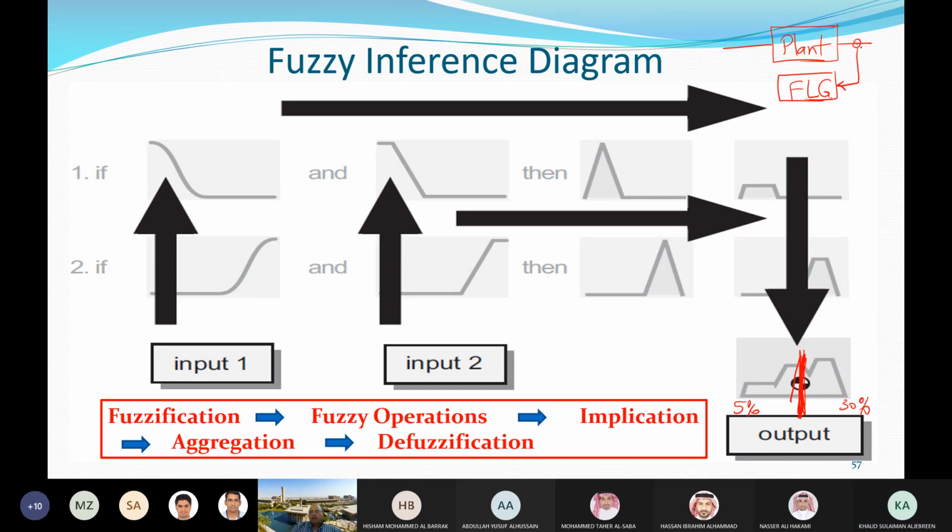You measure pressure, temperature, whatever the quantities that you measure here. So you have some measurements, goes to fuzzy logic. And you have here the knowledge base. Knowledge base, if-then rules, and you do the implication and you do defuzzification and so on. And at the end, you have the output, numerical value here, right?